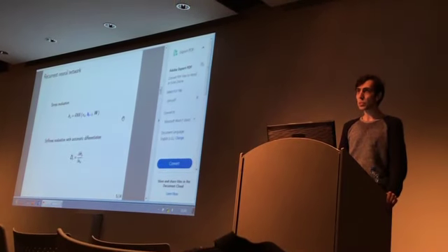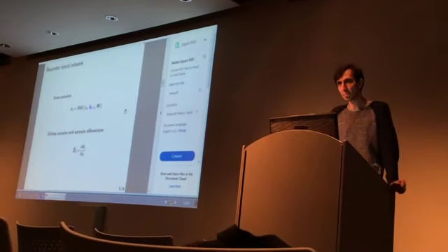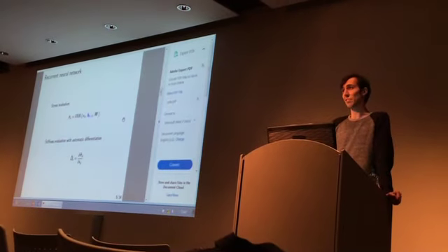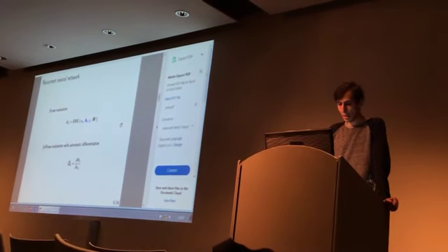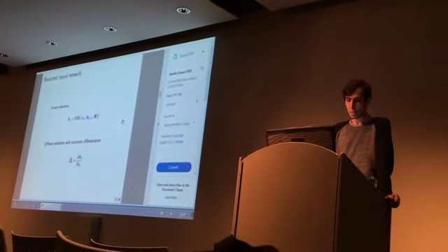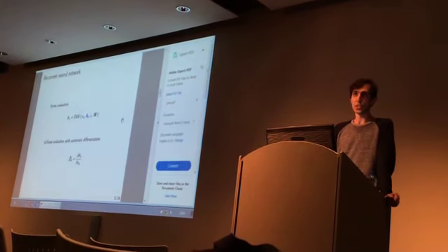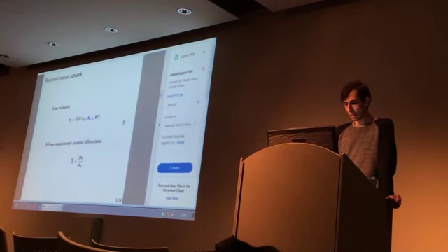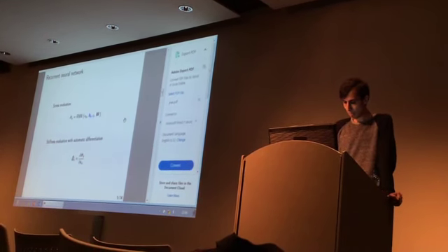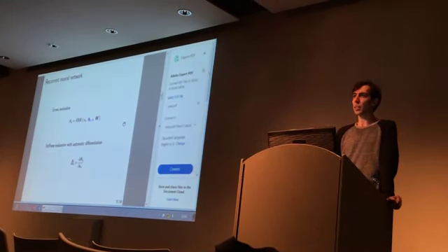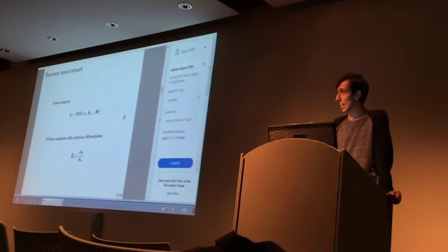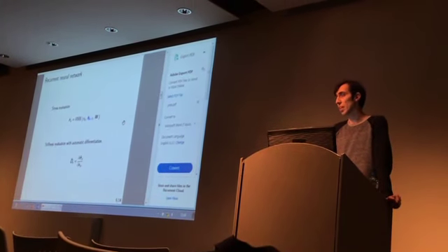If you want to use this model in finite element, we gotta have the stiffness matrix too. To compute this stiffness matrix, I suggest using automatic differentiation. Let me tell you what automatic differentiation is. It's not numerical differentiation because it's exact up to the machine precision.